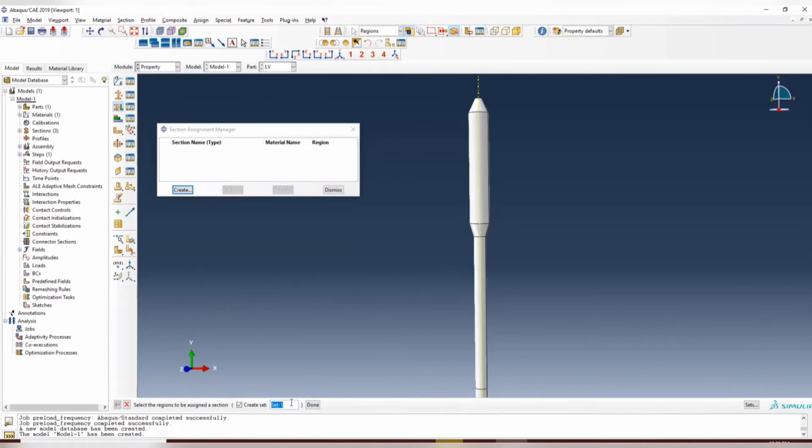So later when Abaqus reports errors, you can go back and check what the error is. So let's call it thickness 0.1. Abaqus cannot use dots for naming, so use P as dot.